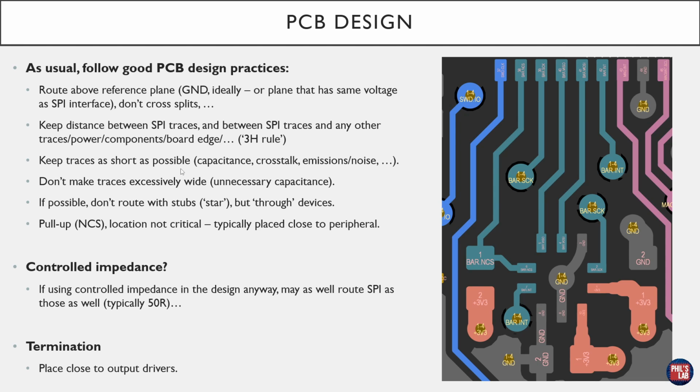Keep traces as short as possible. This minimizes the capacitance due to the trace. It can lower the crosstalk, emissions and noise and so on. So if I can, don't make your traces unnecessarily long or route them excessively.